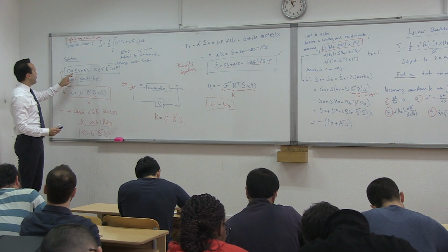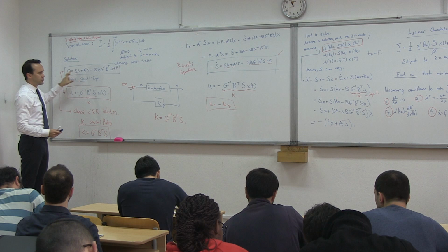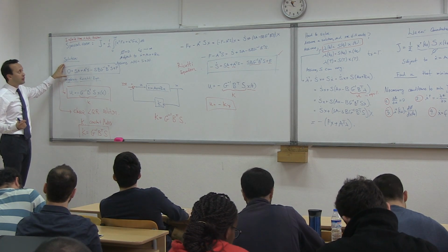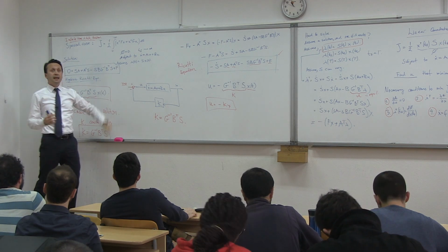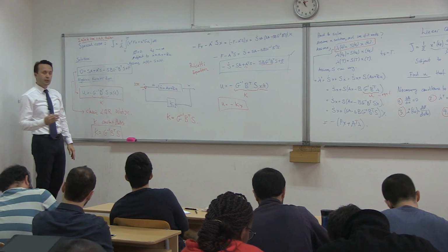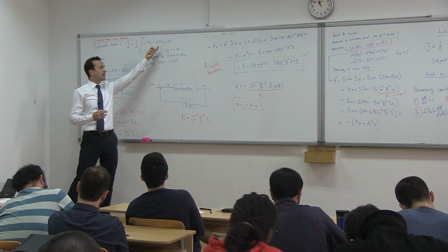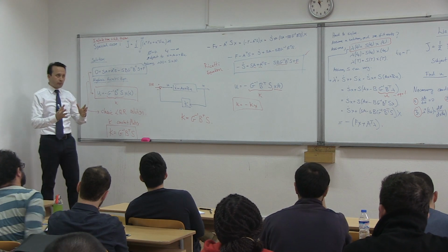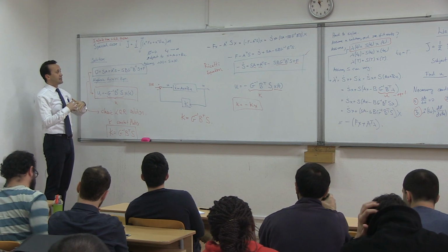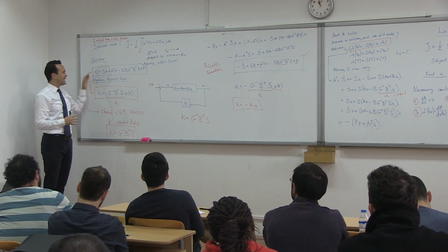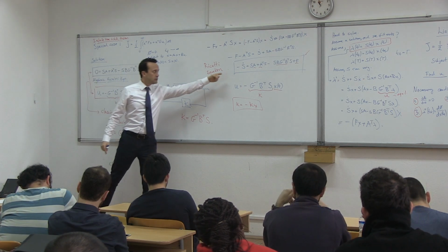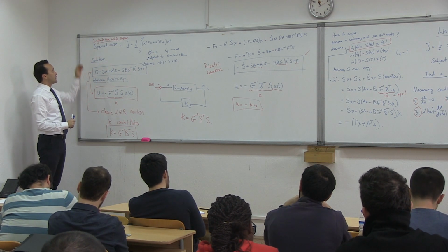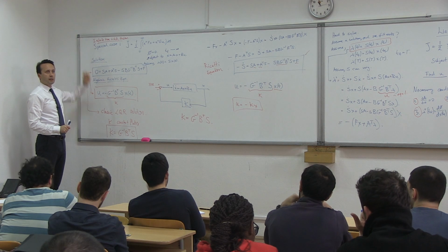And S is a function of A, B, G, and F. That's over here. It's an algebraic equation. It's not a function of time. In fact, this is valid as time goes to infinity. So it will reduce the movement in x and u and really does not look at the final x. Okay? So this is a somewhat simpler problem. Easier to solve since there's no differential equation for S. It's called the infinite time LQR problem.